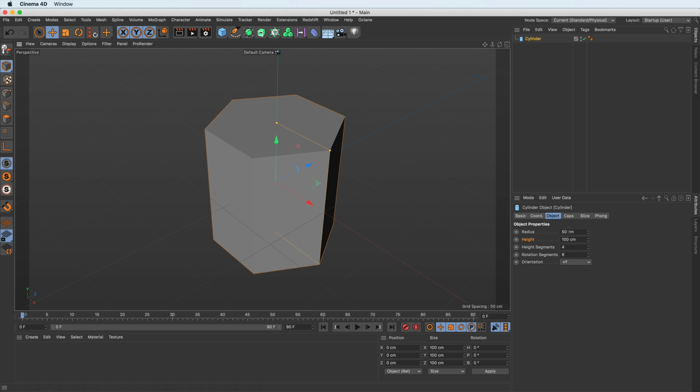And to do that, we're just going to navigate over to the caps menu and turn on something called fillet. Now fillet is just a fancy pants way of saying rounded edges. And if I check this on, you'll see that we just rounded out our geometry here. And you can control the radius of that rounding or fillet by adjusting this radius here by clicking the up and down arrows. Now if I just check this on and off, check out how much detail that adds to our 3D object. You can see all of these nice specular highlights, and this just looks way more realistic. So always add round edges when you have the opportunity to make your 3D look way more realistic.